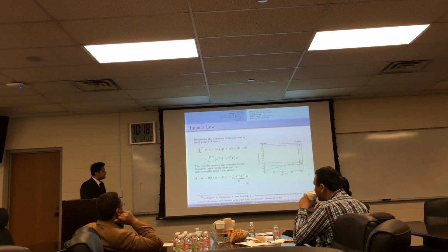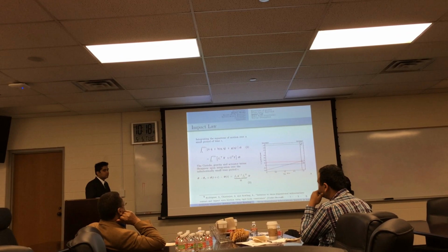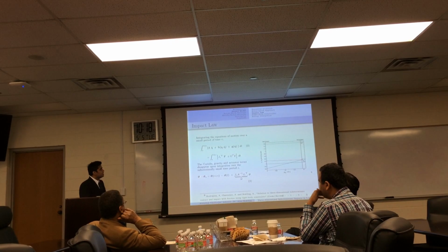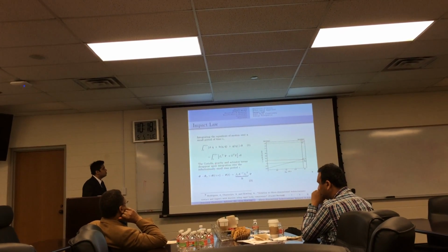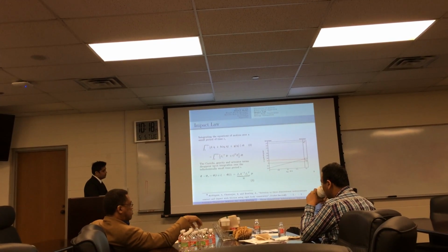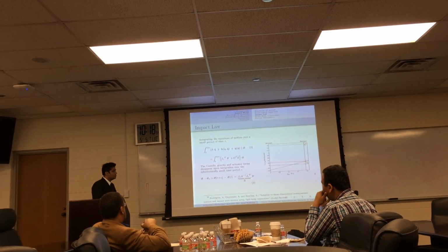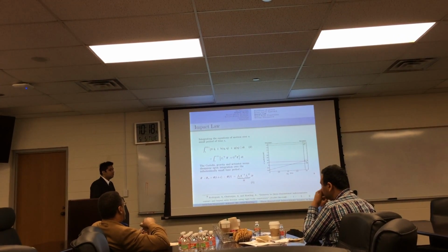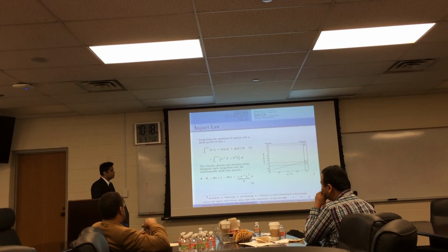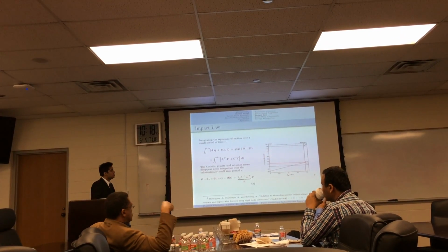So instead, a much better way would be to convert the whole equation of motion into an impulse-velocity relationship, and that could be done by integrating the equation of motion over the small period of time. Note that we said that q remains constant, which means q dot would have a bounded value during that time.